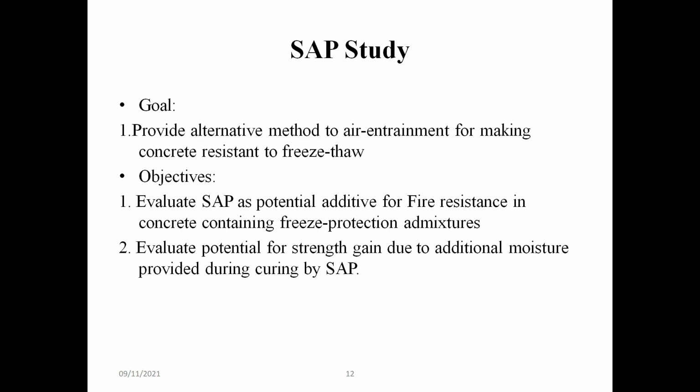Now here we are going to study another SAP study. This time our goal will be to provide an alternative method to air entrainment for making concrete resistant to freeze-thaw or freeze damage. Objective: evaluate SAP as a potential additive for freeze resistance in concrete containing freeze protection admixture. Evaluate the potential for strength gain due to admixture, due to additional moisture provided during curing by SAP.